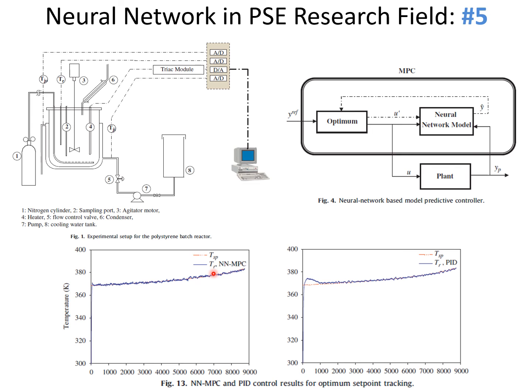more stable and more tight. So again, follow the steps of the modeling: using the right data, good data, enough data, good input-output pattern, good neural network structure, the right activation function, and a lot of testing, training, and validating before you implement. It's not just straightforward. You have to do all this, get it right, then implement it. Again, this is implemented online, but it's trained offline.